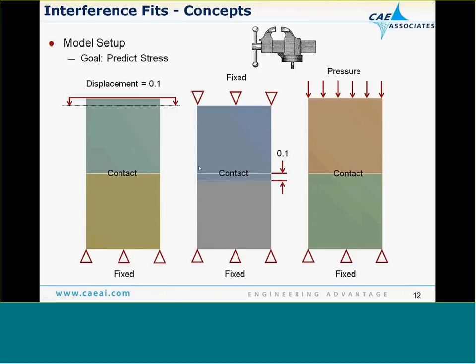And then a second way we could solve this problem is, so this displacement here is at the same level. So this vise is already cranked up to where it was in this example, but we cool these blocks down, thermally contract them, make them small, and then fit in nicely in the vise. And then when they heat back up, they induce some load in the model. Well, we could simulate that process too with thermal expansion, but we could also say just keep these two cubes at room temperature. Those are the original size. Put those in the vise, and we have some physical geometric penetration between these, that 0.1.